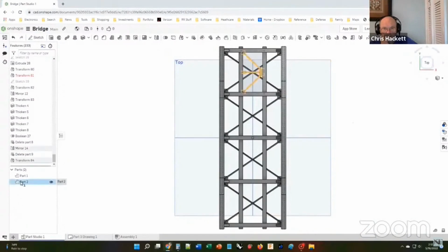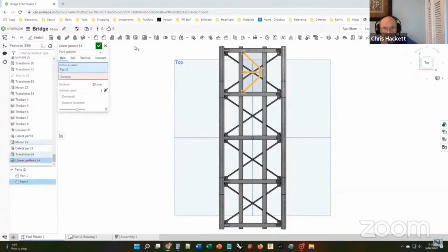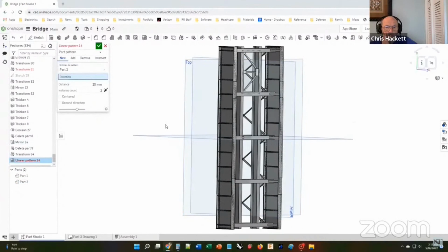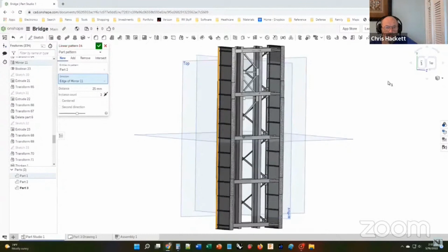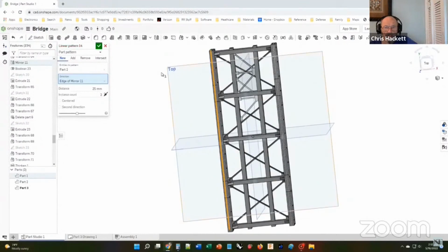There are a lot of details that I didn't include in this bridge construction. At the end of each floor beam are a pair of 6-inch angles to bond them to the girder plate. And at the end of each stringer, there are another pair of 6-inch angles to rivet it to the floor beam. In addition, there's a 6-inch angle under each end of each stringer to support it.